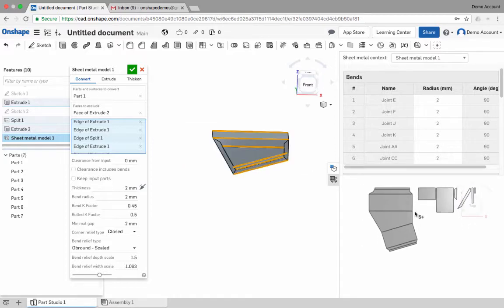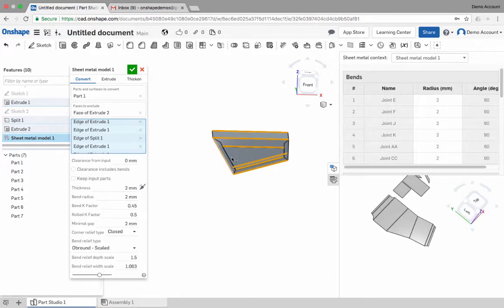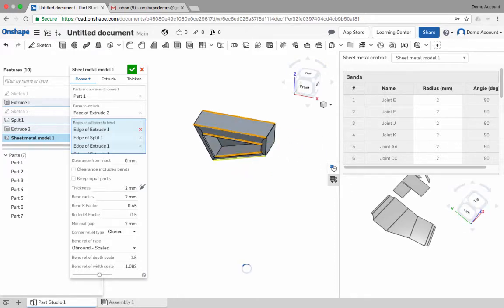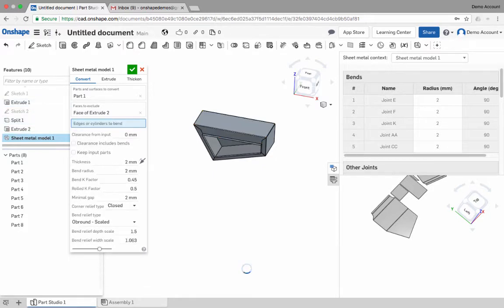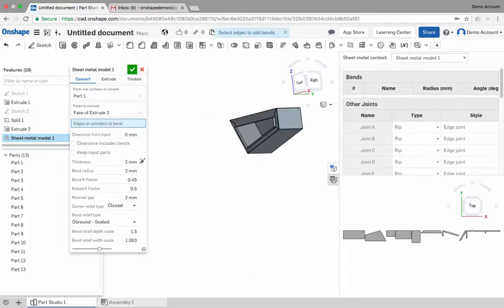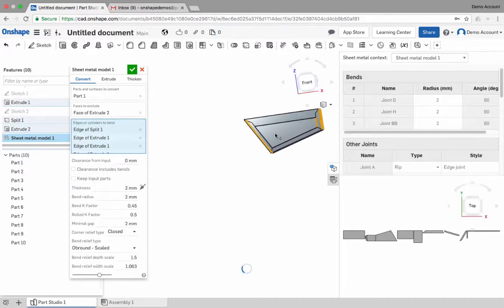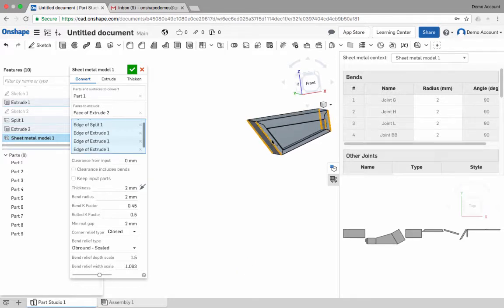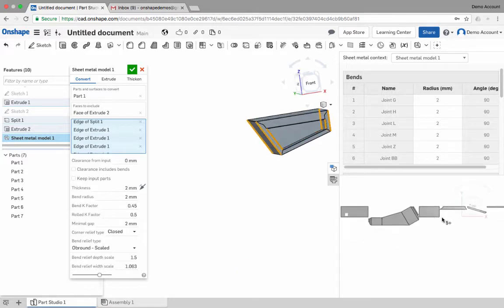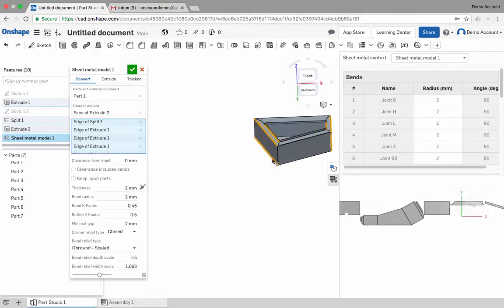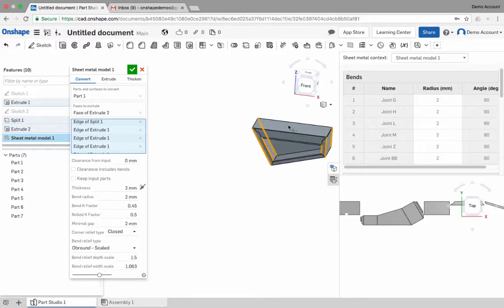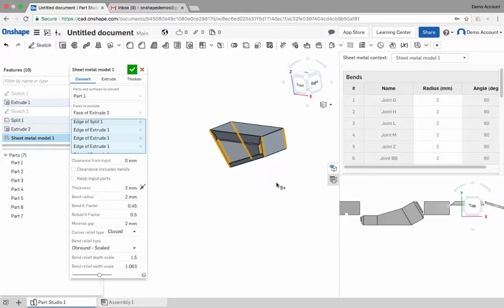So a better option might be here to bend the two end faces around. So what I'll do is get rid of all those, split it all back up, and then we'll put our bends around here. It doesn't matter which edge you actually select, it can be the inner or the outer. So now we've got this shape here, which I think we shouldn't have too much of a problem with getting the press into those edges, as long as we don't make it too short, as long as it's still around about the 500mm long to the 300mm ratio here, we should be okay.